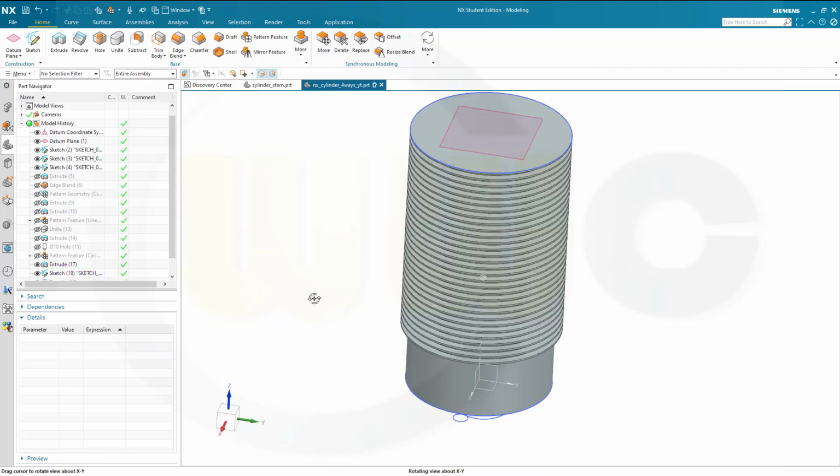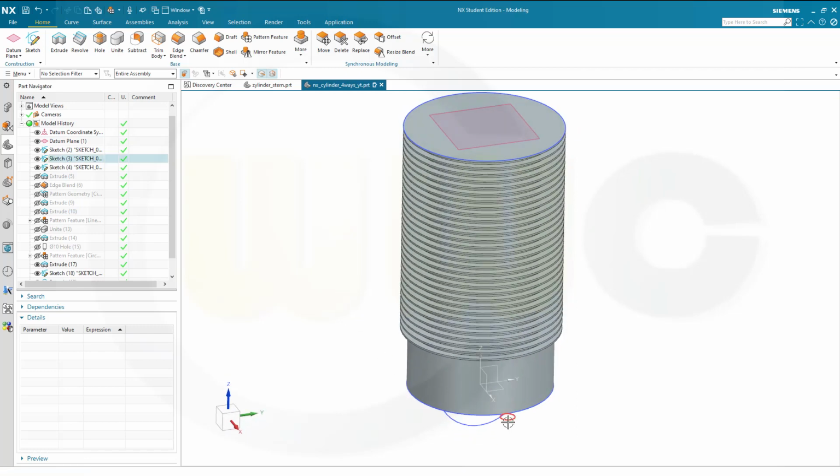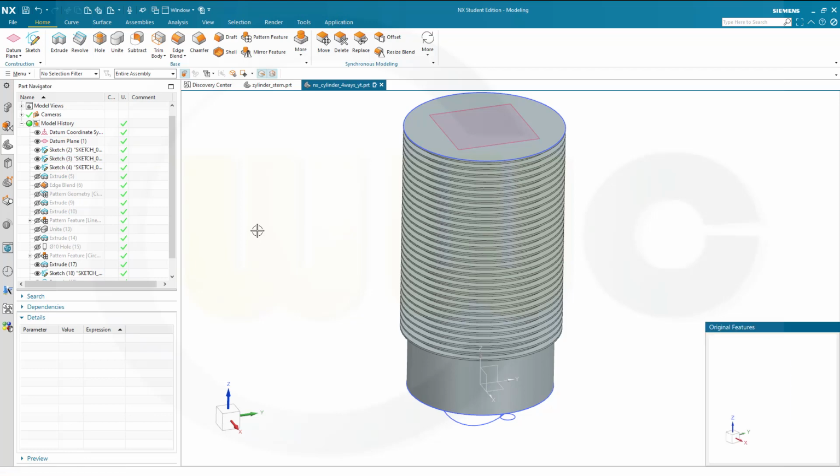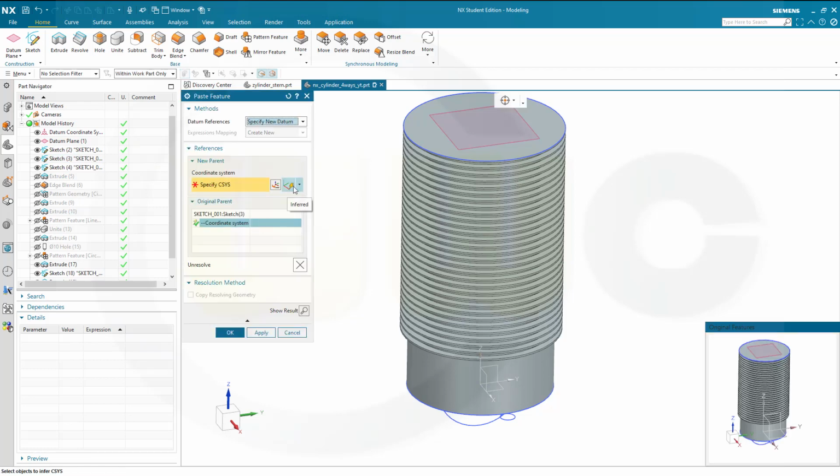Nice. Now again, this one should be up there, so let's go, that's the second sketch here. Let's go for a copy. Paste it, Ctrl V. Again, go for that same kind of new coordinate system. So let's go for that datum plane. Go for the same axis, that would be the y-axis. This one here. And the point would be again that origin point, and confirm.